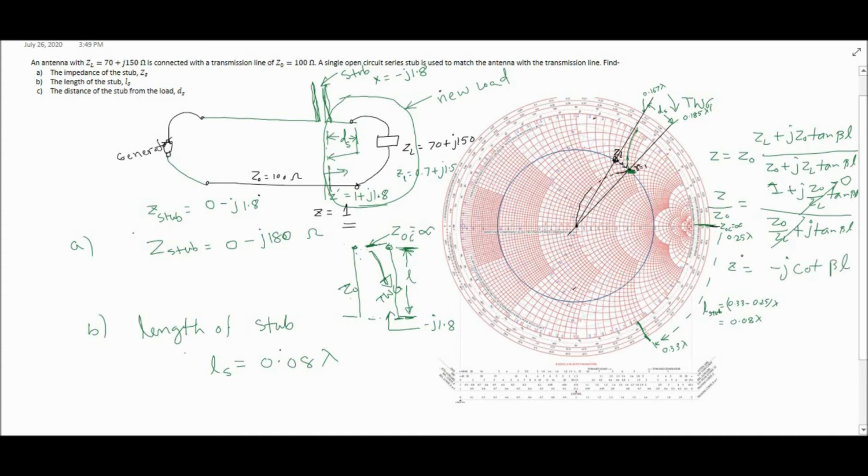So you see here the impedance is like cotangent of beta L. That has a negative imaginary part, and the value is defined from cotangent beta L. Beta L is the length, called the electrical length. If you divide this value by beta, you will get the length. So whatever you got, cotangent of beta L is equal to Z.